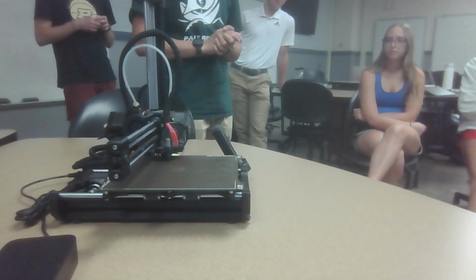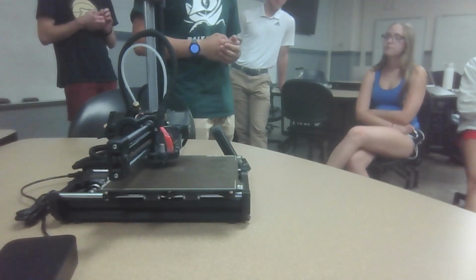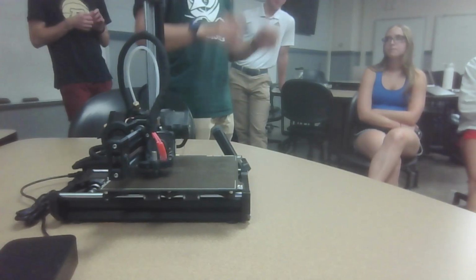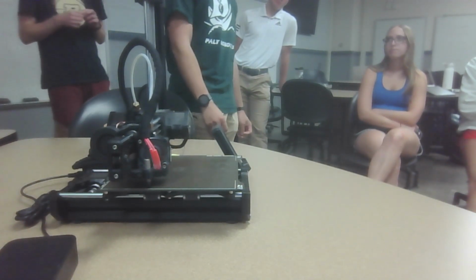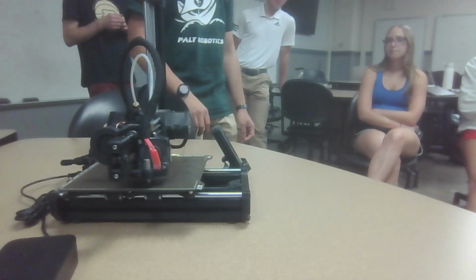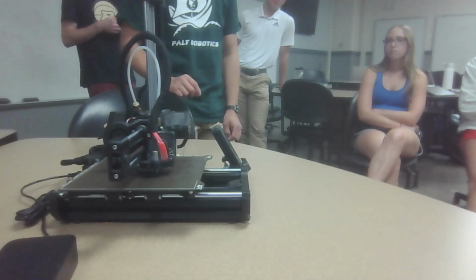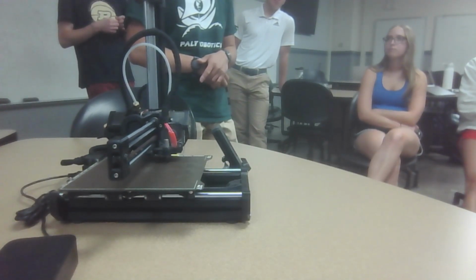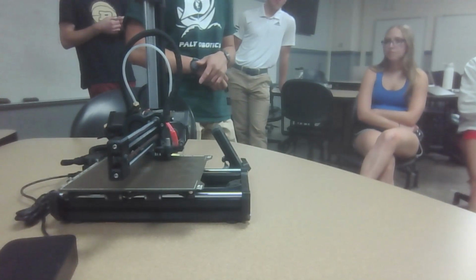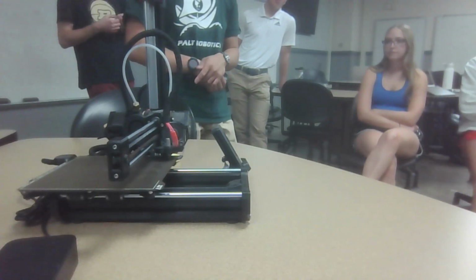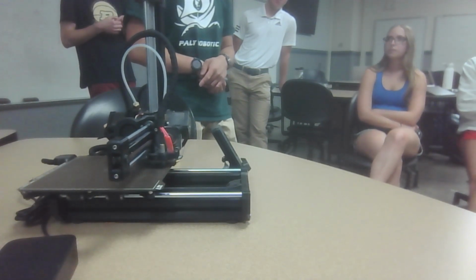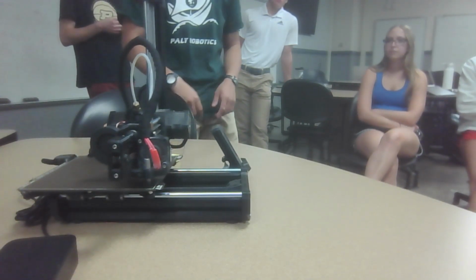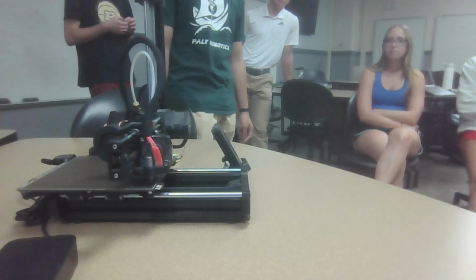If any of you have used an Ender 3, there are knobs on the bottom of the build plate to level it, and it can get tedious and annoying, but this will do it for you. Most printers these days are starting to come with auto bed leveling as standard, so that's nice. But 2 or 3 years ago that was not standard, and you would spend a lot of time being sad and using a piece of paper to level the bed.